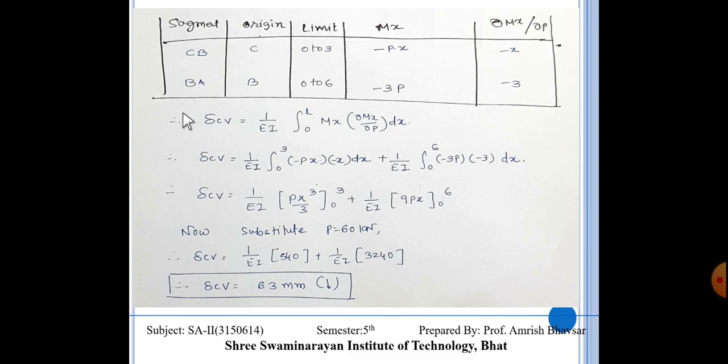Again this is a cantilever frame, so we have to directly calculate the Mx. In the case of a simply supported beam, we have to first find out reactions in terms of P, but in the cantilever case there is no need.